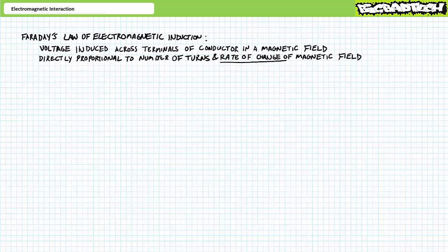This implies it is not necessarily the strength of the magnetic field, but rather the rapidity with which the magnetic field changes that influences the resultant voltage generated. Slowly changing magnetism results in lower induced voltage, whereas rapidly changing magnetism results in higher induced voltage. Prime movers, i.e. the wind, water, expanding steam, or engine turning a generator, need to turn it at a sufficient speed for a usable voltage to be generated.